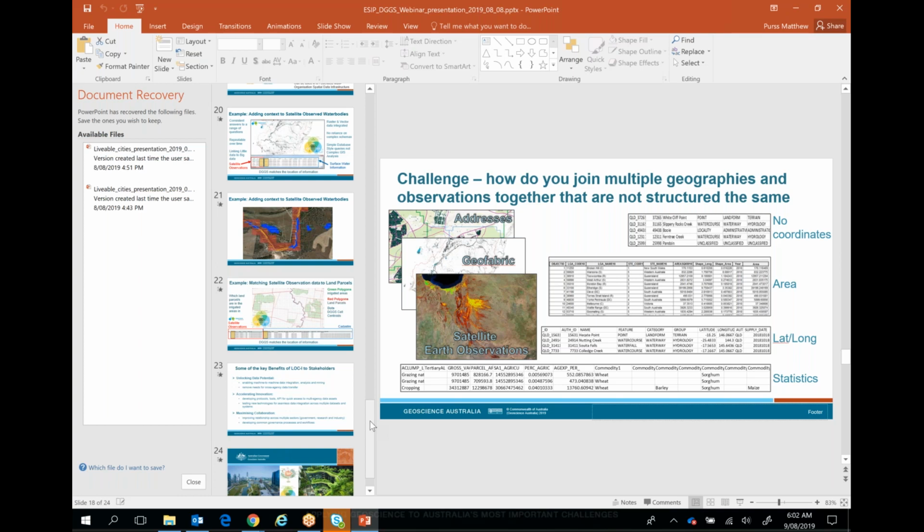The problem with that is, for a country like Australia, or a continent like Australia, from the bottom of Tasmania to the top of Cape York in Queensland, the size of those cells varies by over 30%. So when you're doing analysis of data, you have to correctly reconcile the areal difference of the data stored in those bins.